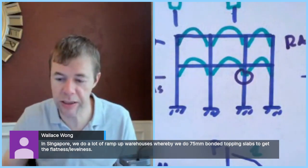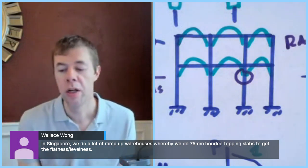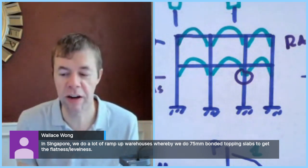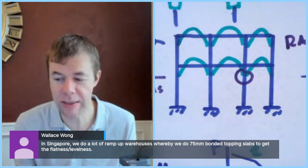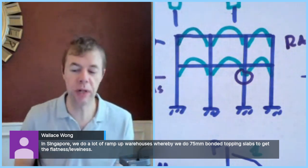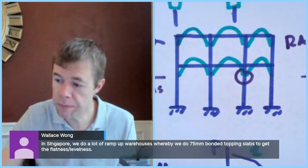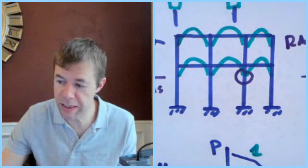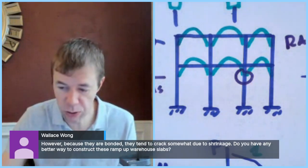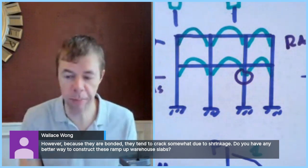So Wallace said in Singapore, we do a lot of ramp up warehouses whereby we do these 3 inch or 75 millimeter bonded topping slabs to get the flatness or level. So 3-inch bonded topping slabs. And then he says, because they're bonded, they tend to crack somewhat due to shrinkage. Do you have any better way to construct these ramp up warehouse slabs?